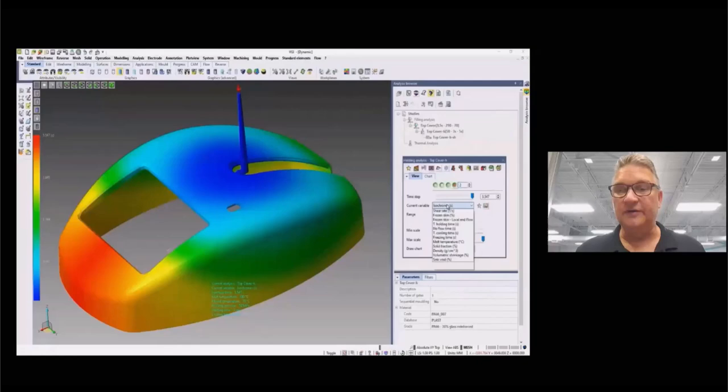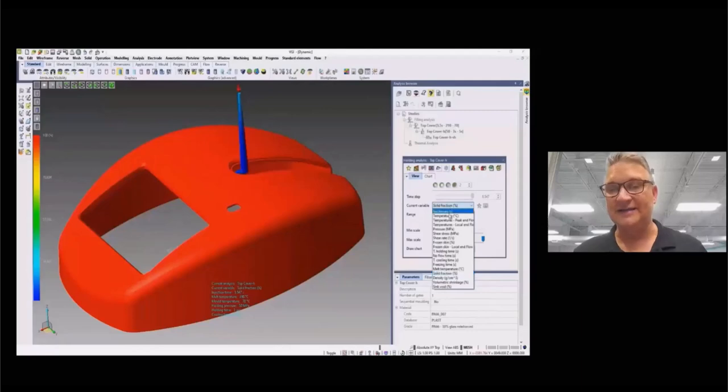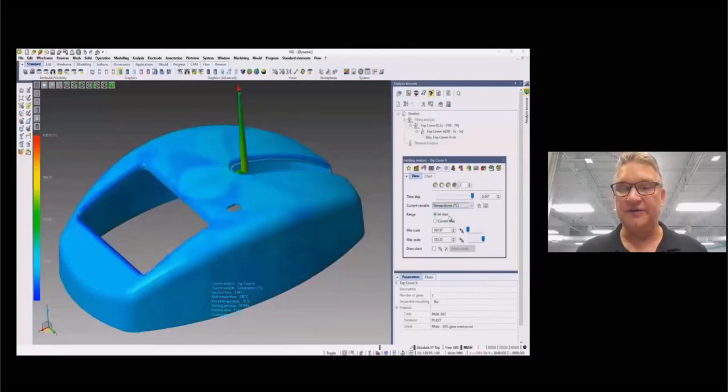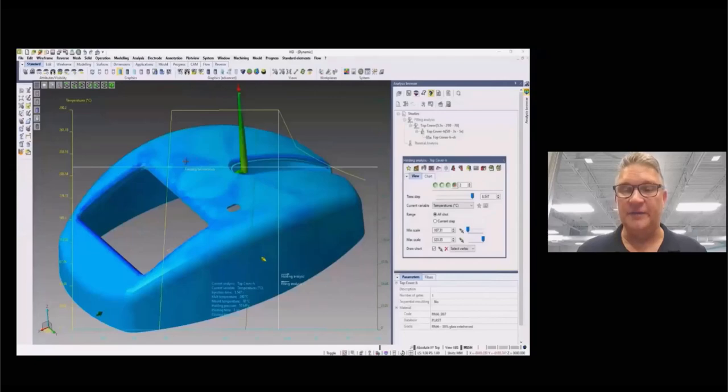Making sure the part is solidified is important not only for cycle time or to understand how the cooling system is affecting the process, but knowing if the part is ready to be removed from the mold. In this case, as indicated, it is a major confirmation of the solid fraction. By selecting some elements, we can review the temperature, which should be lower than the solidification temperature. The program shows a line indicating the freeze temperature within the graph. It helps you to understand when you have reached this moment on an element. In this case, the one selected here is completely solidified.